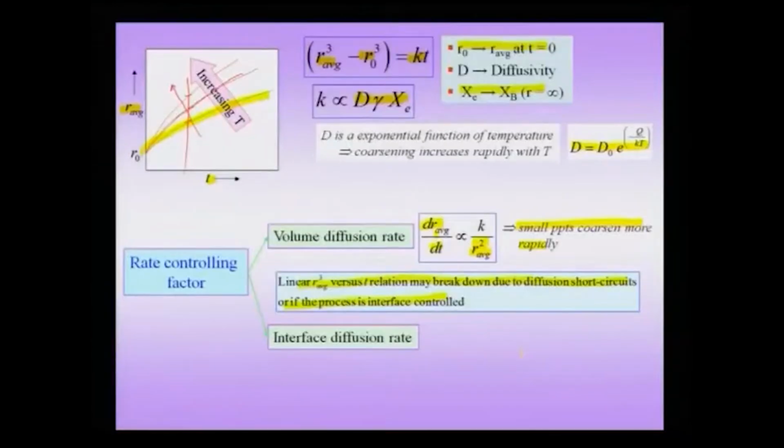larger precipitates. And with time, you will find that you initially wanted to retain a small distribution of fine precipitates to have a higher hardness, and we have already previously done a solved example wherein we have seen how a Frank-Read source operates around these fine particles, which is giving rise to hardening. If these particles are coherent, then in some cases, if the stress is good enough, the dislocations can actually glide through the precipitates, while if they are incoherent, then they bow around the precipitates, leaving dislocation loops around them, which is called the Frank-Read mechanism, or an equivalent mechanism known as the Orowan mechanism.